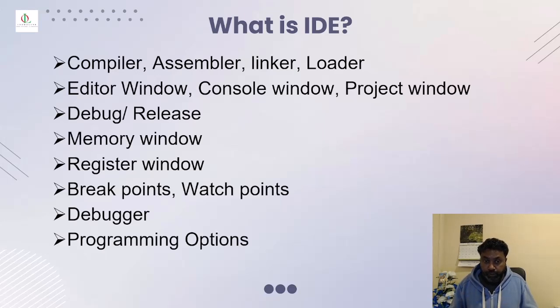And programming options. Some IDEs will have additional programming options for microcontrollers, some won't, so it depends on what IDE is used. For example, on an 8051 IDE, if you use NXP semiconductors, you need an additional flash programmer to load the boot program, whereas this IDE has a built-in functionality, so you don't need an external programmer to program the bootloader. So things like that.